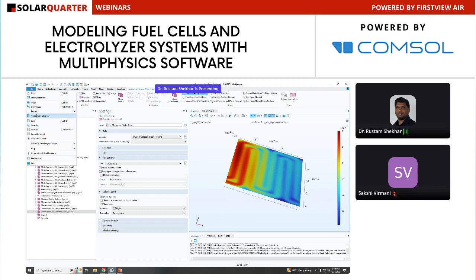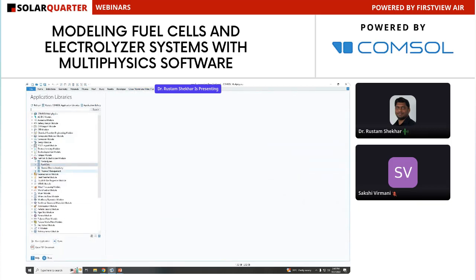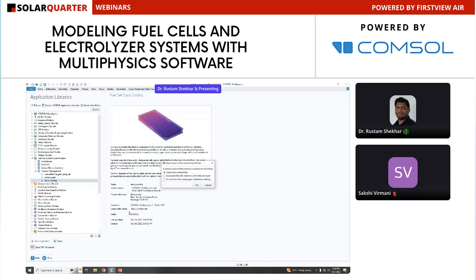One more extension of those kinds of fuel cells can be done, and then you can go for a stack level model. In the stack level model, we can do the cooling of the stack. So here we have five different cells that you can model and see the results for. So this is the stack with the five cells, and the thermal, electrochemical, and the electrical profile of that stack has been modeled.